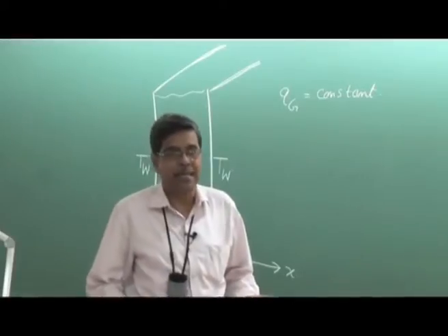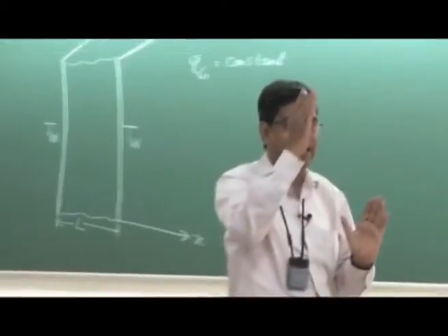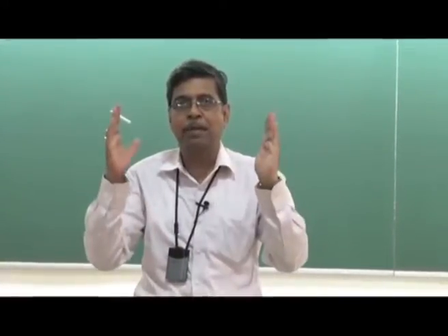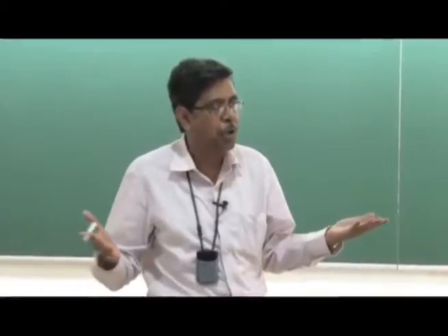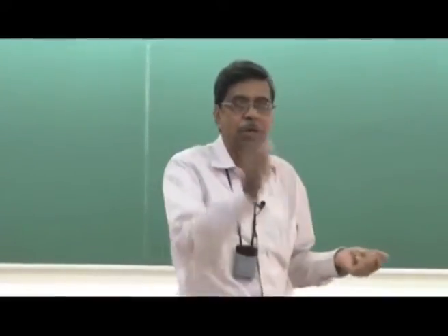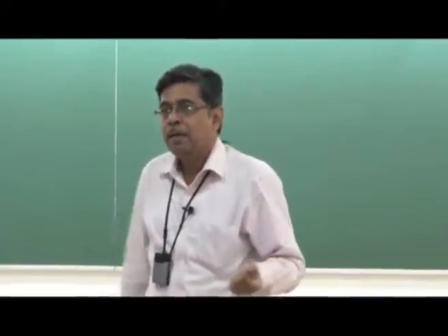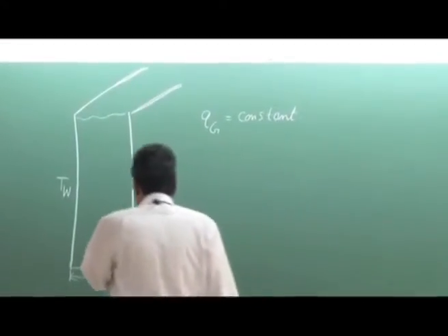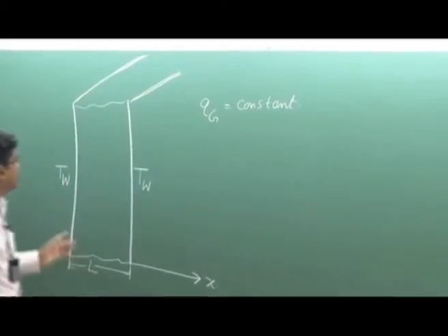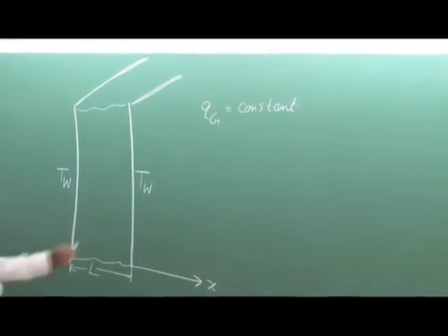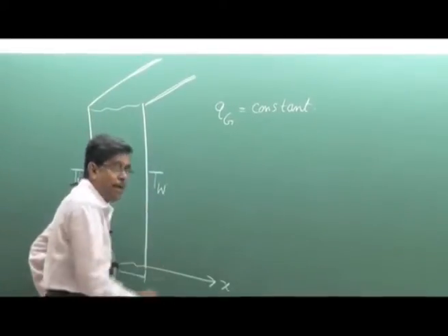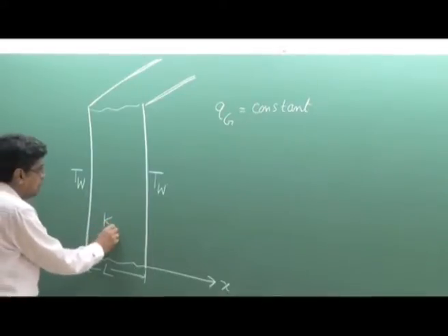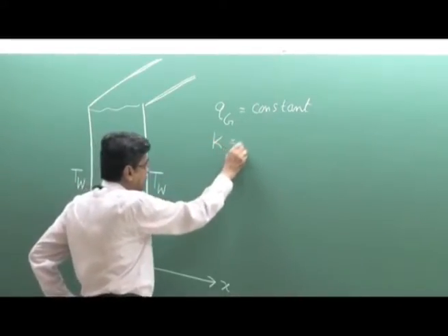So heat will automatically flow when the temperature rises because of the energy generation. It is not necessary that one surface has to be at a higher temperature than the other. For example, without any generation of thermal energy, with both surfaces at the same temperature, there is no heat flow, unless you initiate the problem by making the temperature within the solid higher. This is being done by the heat generation. Now, the starting point of this problem: the thermal conductivity k is constant.